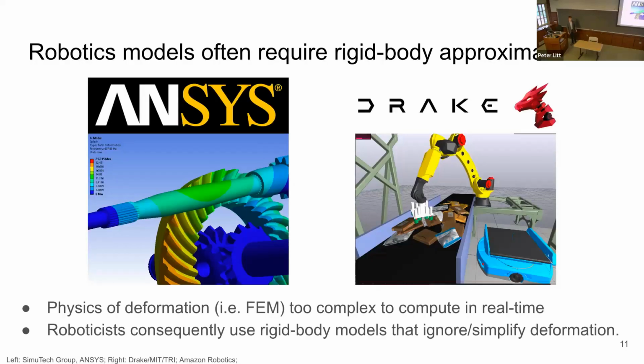So while these robots that we're describing may be designed with high fidelity solid mechanical models, for instance, with finite element analysis, when we embed models into model-based control, we need them to be able to make predictions of dynamic behaviors through time at faster than real-time rates. So we simply do not have the computational budget to be simulating physics in this level of detail.